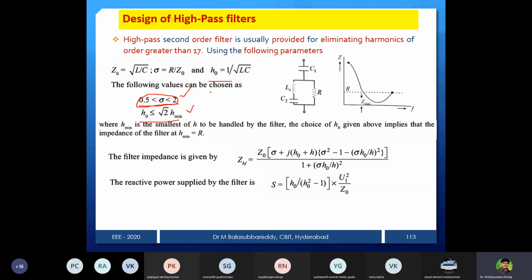And some components inside depend on whether it is capacitive in nature or inductive in nature. If it is capacitive, it will be supplied, or if inductive, it is going to be absorbed. So that is all; there is SVC or any FACTS components you can use, StatCom you can use, and UPFC, that is compensation. That is an entirely different subject in FACTS. You can take it as a simulation experiment also.